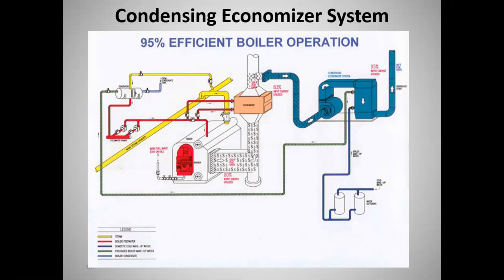Okay, so there's an example of a condensing boiler application. So let's see what we got here. The pink box sitting on top of the flue, that's the standard economizer right over here with the red pipes. Here, let me use my pointer. We have steam coming out of the boiler to the main steam header. Here are our pumps and deaerator, we're pumping back, and we go through this heat exchanger and we preheat. So this is a standard economizer.